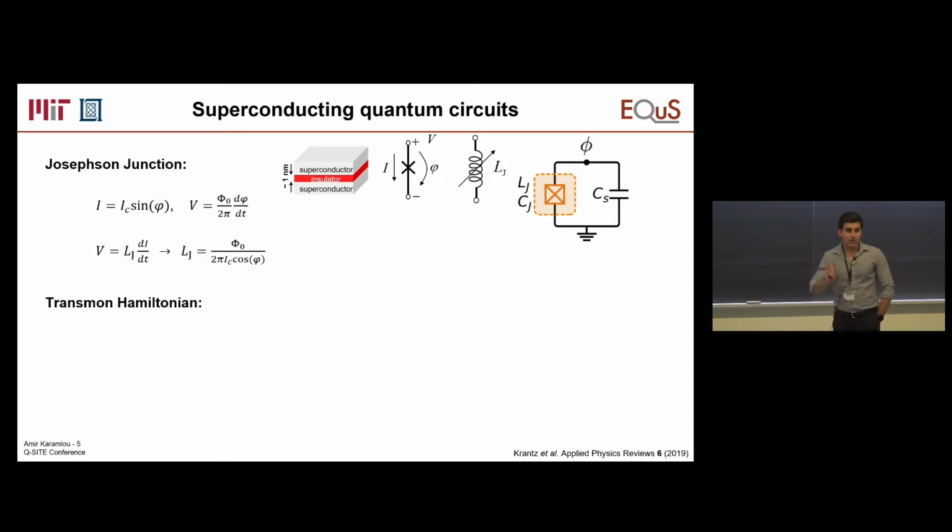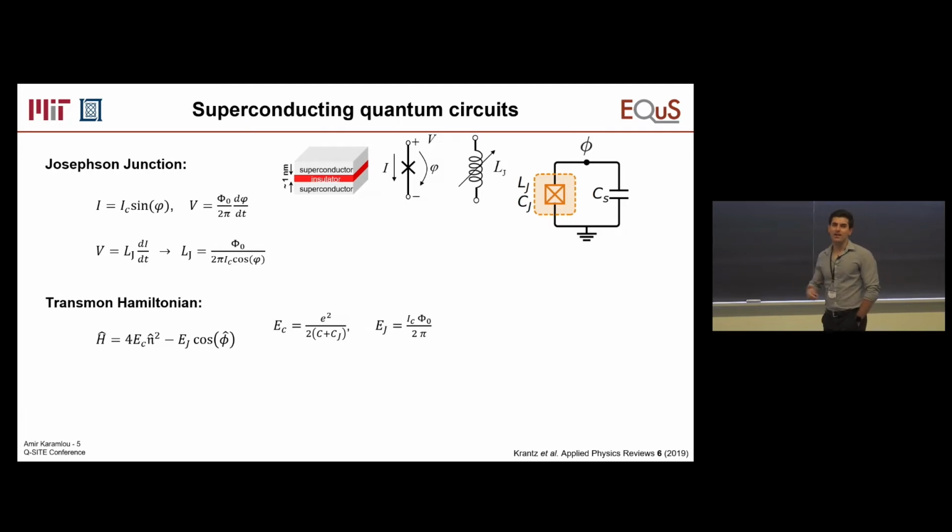So with that, I can build a qubit out of this, actually, and I'll tell you guys why. On one end, I have my capacitor from the LC circuit that we discussed. And on the other end, I replace my inductor with this Josephson junction that, again, is a nonlinear inductor. Now, let's see what happens when I do that. The equation that I had for the LC oscillator, the Hamiltonian, will look something like this, where now the energy of the Josephson junction has some dependence on the critical current of the junction. And this is something that we can actually engineer in fab.